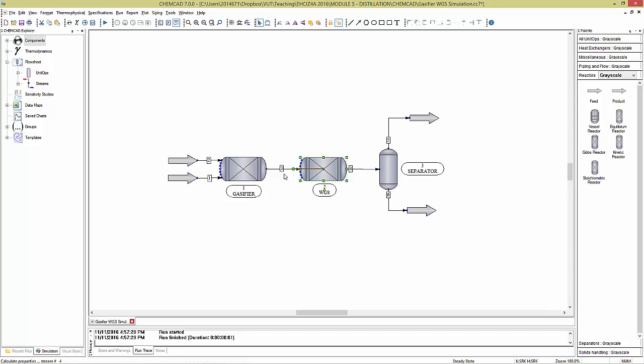If the pressure needs to increase, I need to see a compressor. If the pressure needs to reduce, I need to see an expander or a valve. If you're feeding steam, I need to see where the steam comes from. Usually you are given water, steam is not available on site. I need to see you boiling the water to form steam that you're going to feed into your system.